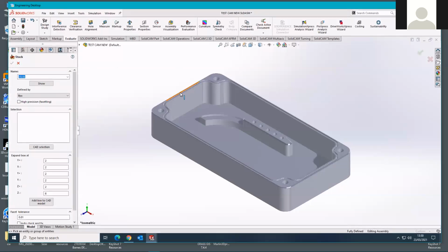So yeah, we're going to create a block of material which is going to be slightly bigger in our case than our finished box size. That will allow us to machine a certain proportion of that material away and arrive at our finished box size and shape, having machined the faces of the box, rather than the alternative, which would be ordering up a block of material that was touching the outermost faces of our box, in which case we couldn't run a cutter along those faces because they would already be on size.